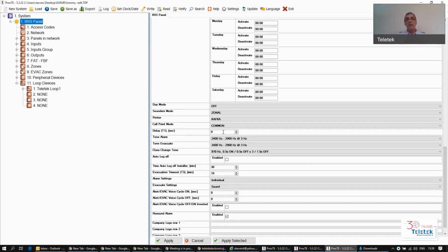In case of fire, there is no need of action from security personnel on the panel screen in order to start the delays that you set up by the zones. If you put a number, it's in minutes. If you put any number different than 0, the settable time is up to 60 seconds. Sorry, not minutes. The settable time is up to 60 seconds.